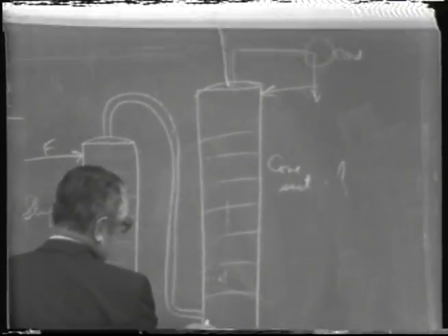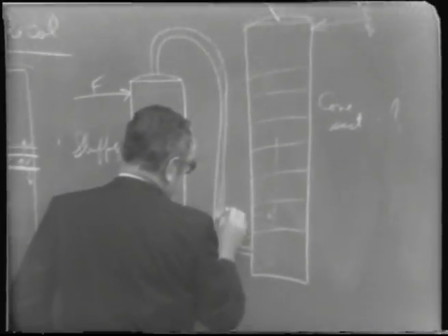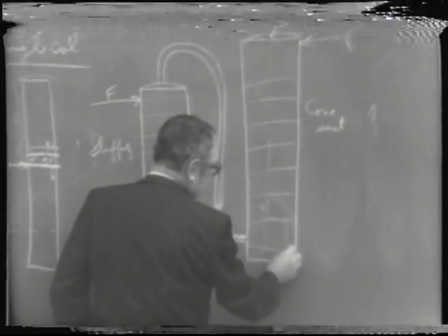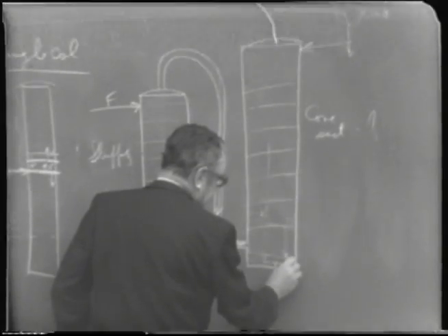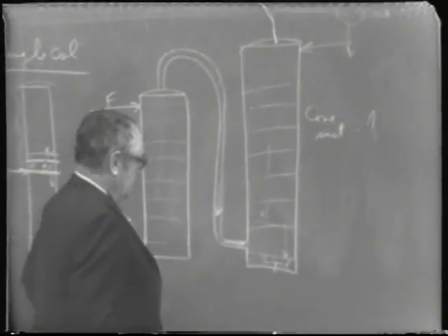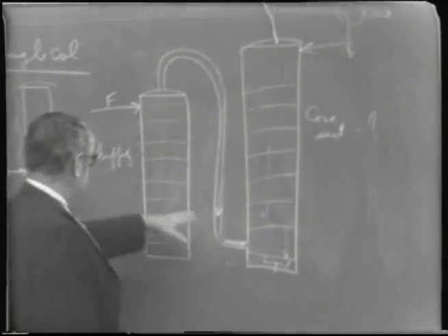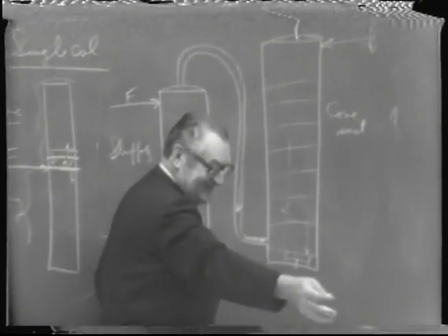And so then you see the vapor comes in, you have to have the vapor being conducted into this section. Now the overflow from this tray is going to produce a liquid phase down here, which has a considerable amount of alcohol in it. It's in the middle of the column, and so you can't throw it away.